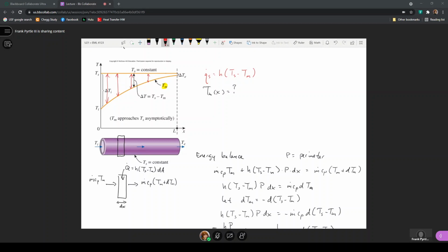So whatever the average heat transfer coefficient is, or here actually we can consider local values of the heat transfer coefficient, times the temperature difference between the surface and the fluid will give us that local value of the heat flux. But a heat transfer rate is equal to a heat flux over the surface times that surface area.